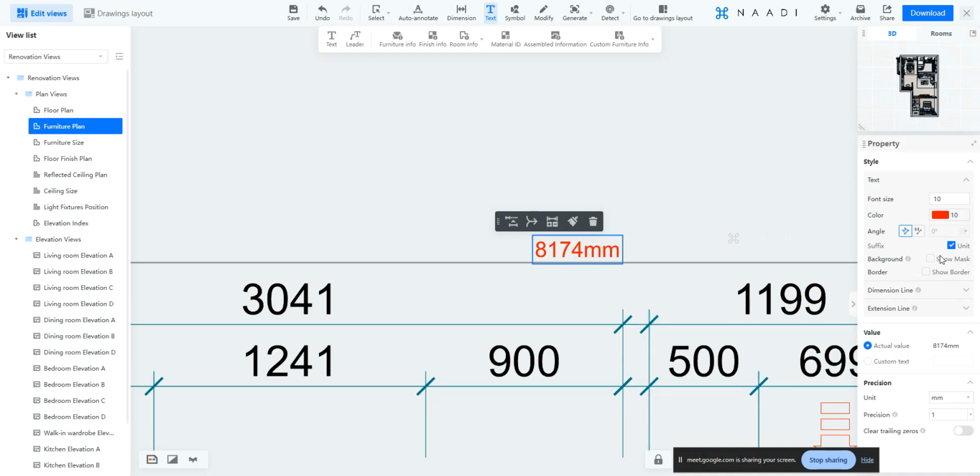And obviously it is understood that this is mm, my project unit is mm, the dimensions are in mm, right? What if my project unit is in mm, but based on your contractors' or your client's requirement, you want your drawings to be in feet and inches? Or let's just say that your model is in feet and inches, but if you want to take it to production, your 2Ds need to be in mm. In those cases, you don't have to change the model unit. I mean, obviously, if you change the model unit and come here, it will be updated. But you don't have to do that.